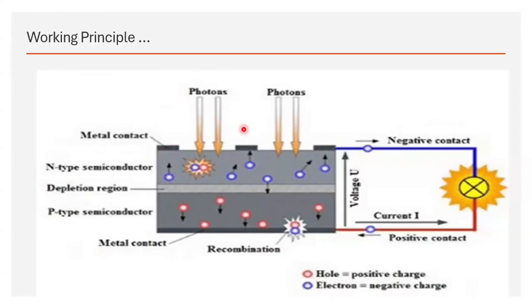So what happens when the solar radiation falls on a solar PV cell plate? The photons, the small packets of energy, small quantums of energy, help the N-type semiconductor to lose its loosely bonded extra electron. So that's why this upper layer acts as a source of electrons, and definitely this upper terminal becomes negative. Now this p-type semiconductor at the bottom has a great affinity to accept one electron. Therefore, when we connect this top layer that is negative and bottom layer that is positive to a load, there is a flow of current and the circuit completes.